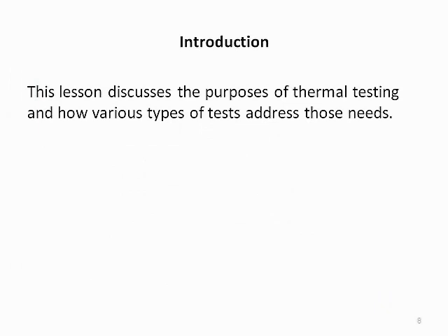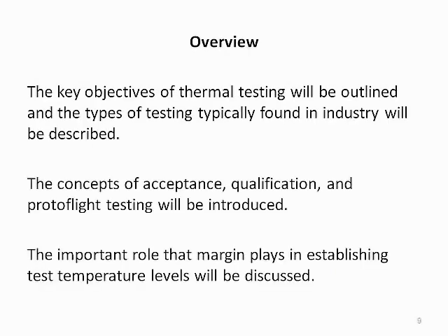The purposes of thermal testing and how various types of tests address those needs will be explored. The key objectives of thermal testing will be outlined, and the types of testing typically found in industry will be described. Next, the concepts of acceptance, qualification, and proto-flight testing will be introduced. Finally, the important role that margin plays in establishing test temperature levels will be discussed.